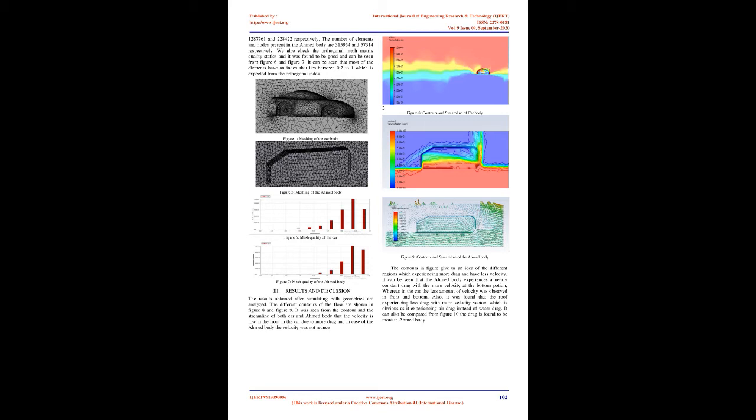The entire simulation was based on multiphase flow, so two phases, primary and secondary, were chosen, with air as primary and water as secondary. The model used in the simulation was the k-omega SST model with open channel flow. Boundary conditions for the inlet and outlet of the water flow were given, and in the report definition, a drag was considered which would occur due to resistance between the vehicle model and water. The entire simulation was carried out in steady state and hybrid initialization was done before running the calculations. Figure 1. Methodology of the approach.